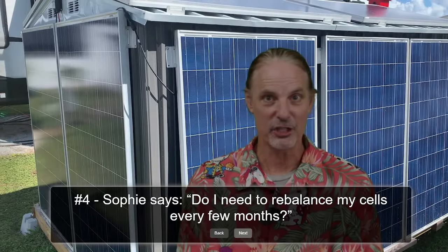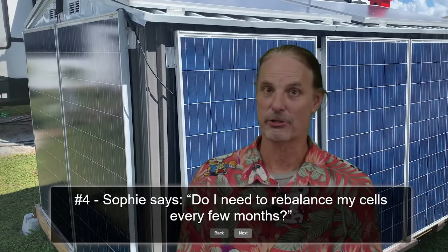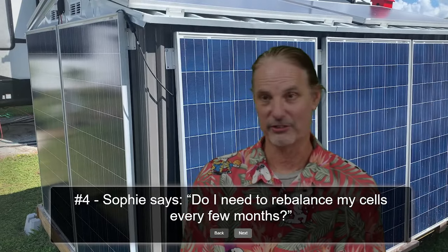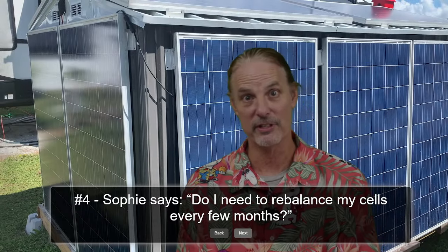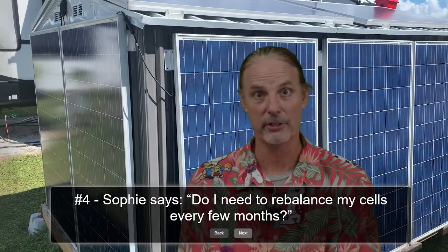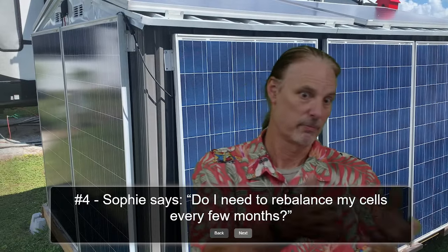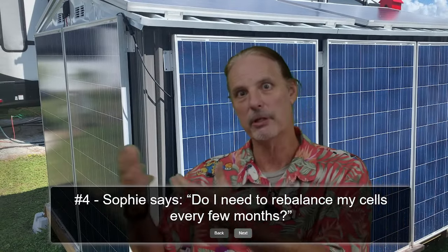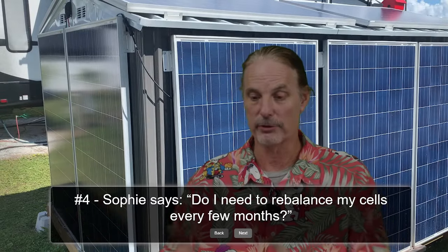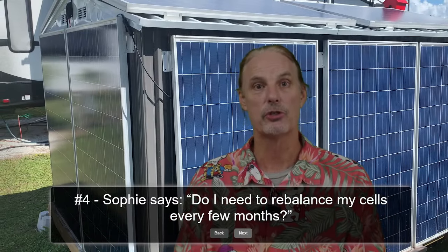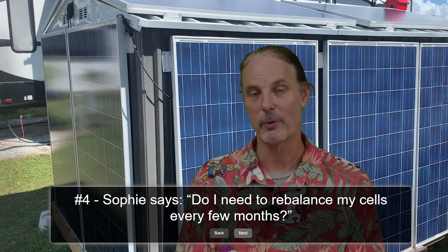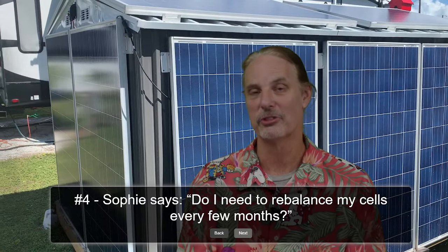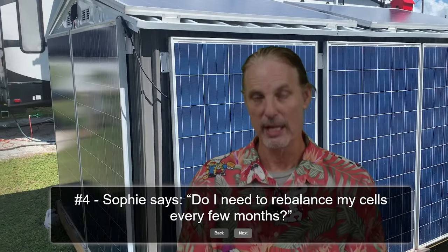So if you have EG4 batteries and you're running into this problem where your state of charge isn't accurate and you can't seem to get it to go to 100%, it sits at 99 or 98 or 97 all day long because the BMS thinks that it still needs 5 amp hours or 2 amp hours or whatever the case may be, and it can't give it because the battery won't take it because it's saturated at that voltage, then what you need to do is change your charge voltage to 56.8. And when it hits 56.6, it will reset to 100%. And then you can turn it off if you want.